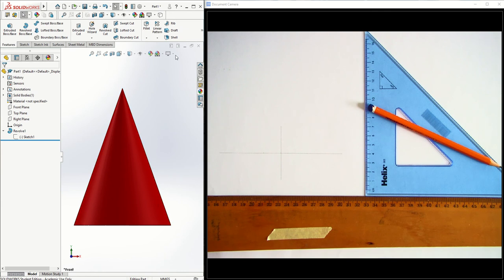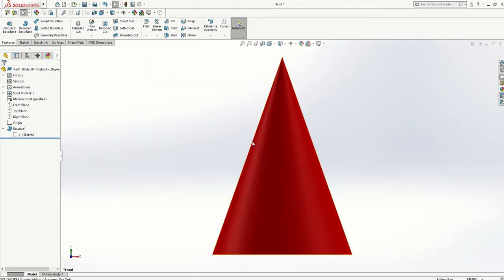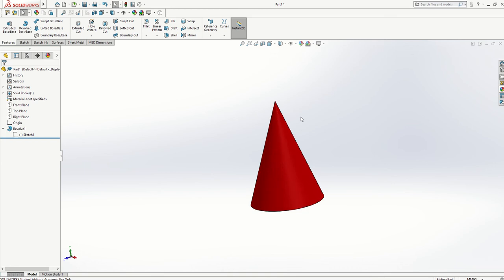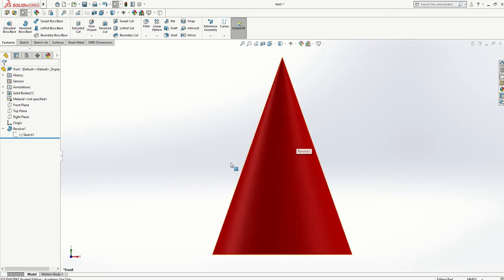Okay, so first of all, where do we get our ellipse? Where does the ellipse come from? Here I have this cone. It's the form of all conic sections that we get. So I just want to show you how we actually get a circle or an ellipse from a cut section of a cone. This is an isometric view of my cone, and this is going to be a front elevation. When I look in the front elevation, it just looks like a triangle.